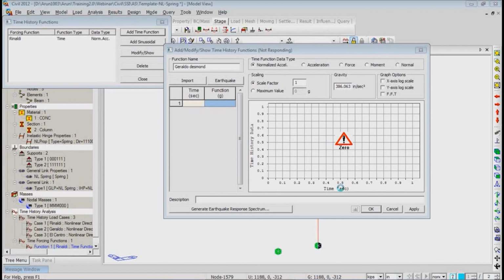Once we have defined that, we'll apply them as ground acceleration onto the structure. Just like last time, we'll also define some time history result functions that are graphs, for the link element's displacement and force, so that you can see the hysteresis loop formation there.